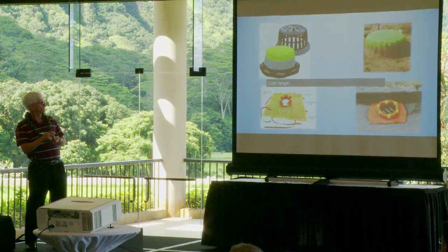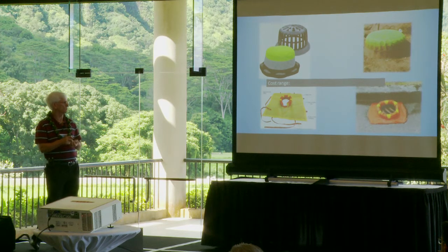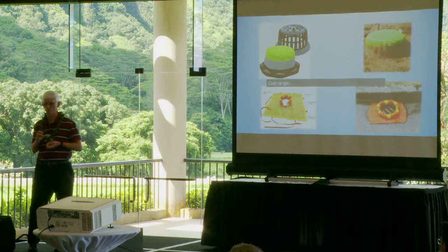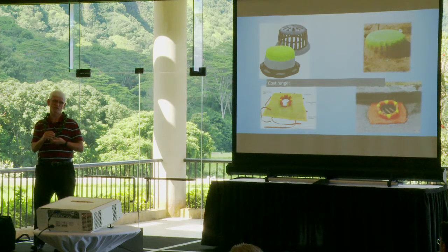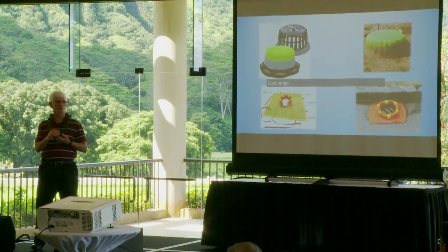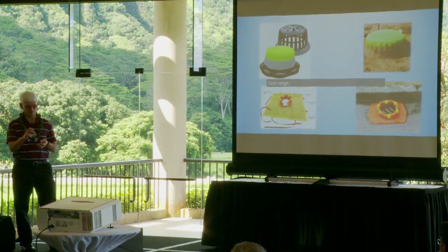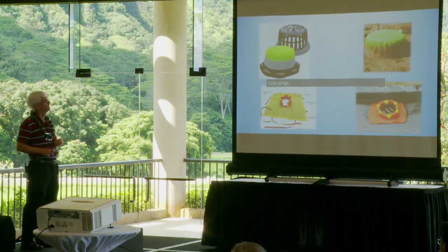There are also devices that can be secured to drop inlets, some by magnets, some by straps. Some of them have a little bit of a riser port on them, but again, they have that overflow capability. So look for overflow capability in your inlet protection devices if you're looking for long-term, I don't want to have to mess with it. If you don't have overflow capability, you'll be doing a lot of repairs and maintenance on it.